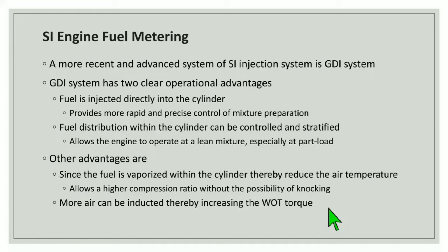The GDI system has some other advantages. Since the fuel is vaporized within the cylinder, it reduces the air temperature, which allows a higher compression ratio without the possibility of knocking, and more air can be inducted, thereby increasing the full load torque.